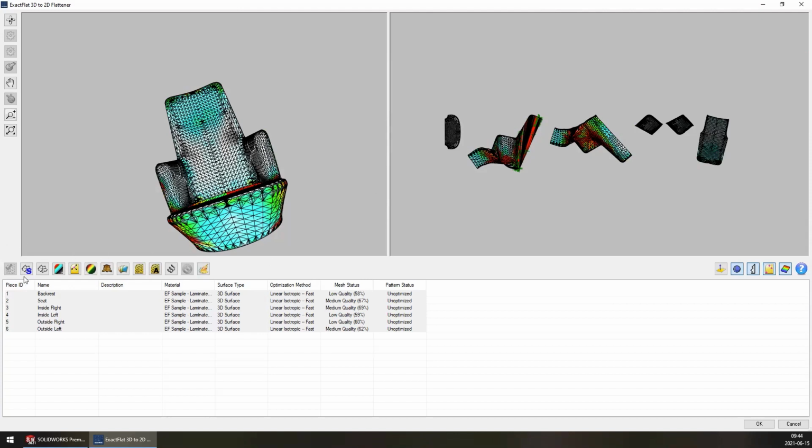Moving on to the flattening controls. Our first group of buttons here are our pre-flatteners. Starting from left to right, we have our Smart Fracture Pre-flattener, we have our Fracture Pre-flattener, we have Stretch Initial, we have Stretch Minimal or De-wrinkle, and we have Stretch Round, and lastly we have Pelt.